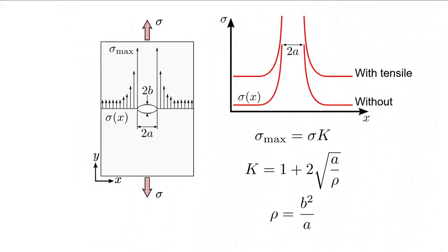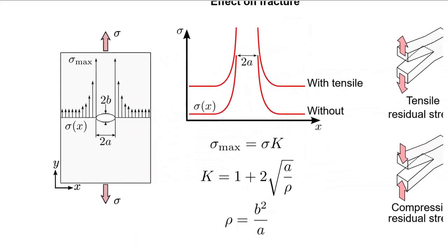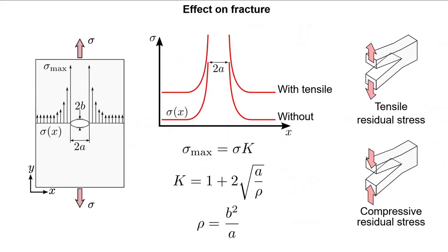To illustrate this point a bit further, a tensile residual stress acts in concert with external loading, so any far-field stress surrounding a defect or flaw is raised to a much higher maximum stress. Note that the stress concentration factor does not change in this circumstance, but the maximum stress obtained does. This means that a tensile residual stress will increase the crack driving force, while compressive stresses will decrease or even